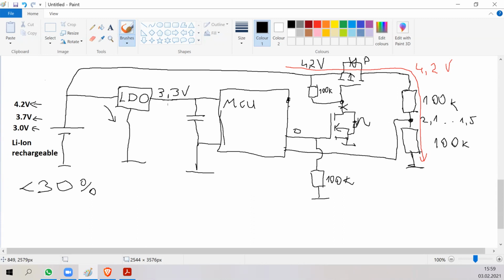So it was just constantly discharging the battery to the point where it was almost damaged. Fortunately, our batteries all have this protection board, so the battery just discharged to 3.0 volts, and then the protection circuit just disconnected it entirely, so it didn't keep damaging itself, but still, it was a disappointment.